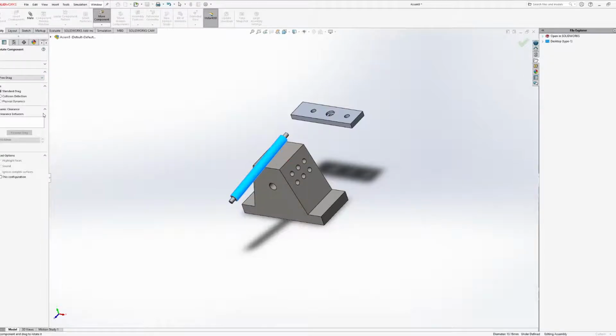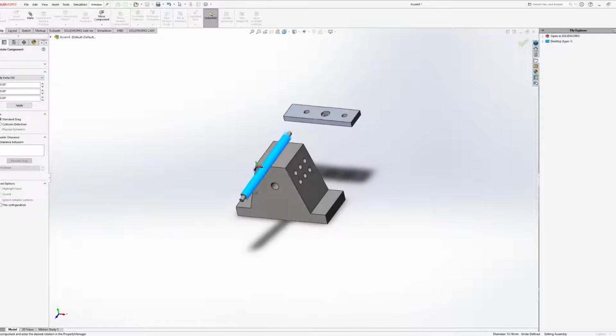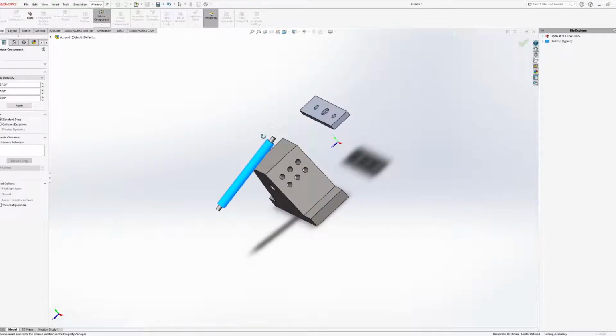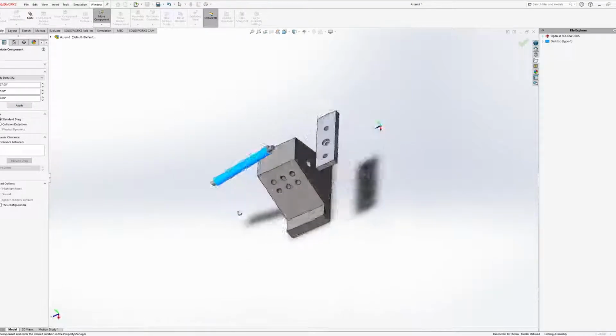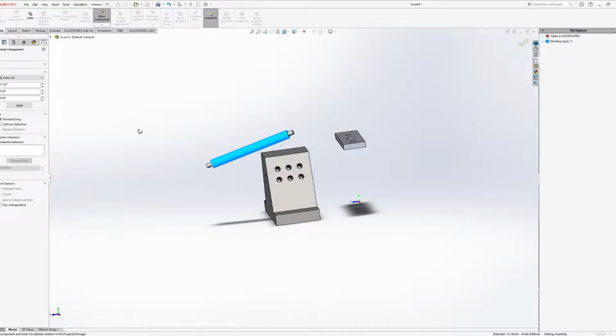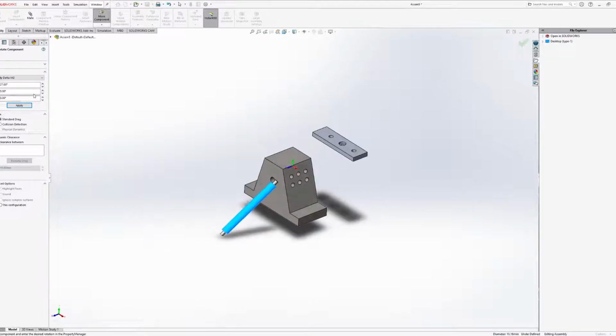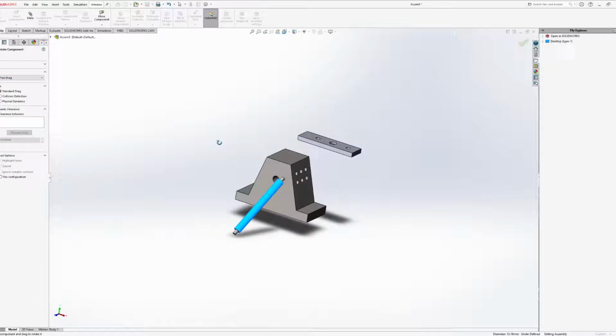If we want to rotate, we just have to hit this rotation drop-down menu, and it has fewer options, but they're all very similar. We can do it along an entity, or if we know an exact rotation that we might want to turn it to, we can just set it to that. So maybe I want to turn this 27 degrees along the x-axis. It should rotate either clockwise or counterclockwise from my view. I would assume counterclockwise? Okay, I think it's more about the actual axis that we're dealing with. So it's rotating about the global axis, but that still was counterclockwise. Rule of thumb, we generally take counterclockwise to be a positive direction.